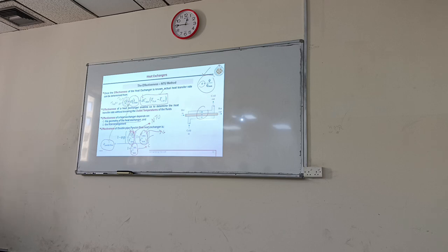How do we know U? We need HI and HO. For fully developed flows, MCP product is given, mass flow rate is given, area is given, so it means you know the configurations also. So we can find out HI and HO, and find out U. If you cannot find it, do an experiment and find out U. Anyways, so this is for parallel flows.